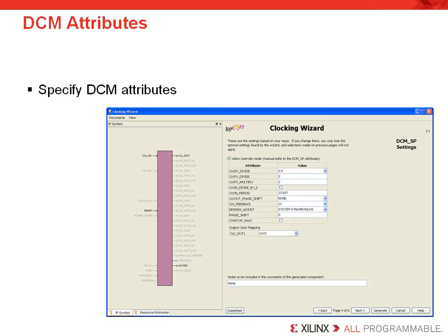After you've customized your MMCM, the attributes made by the core generator are reported back to you. You don't actually have to do anything with these attributes, but they are reported and included with the instantiation of the component you created. This is helpful in case you decide to place your attributes directly in your design's UCF file. The UCF stands for User Constraints File and is a repository for all Xilinx-specific attributes. This includes pin assignments, timing constraints, and design attributes.